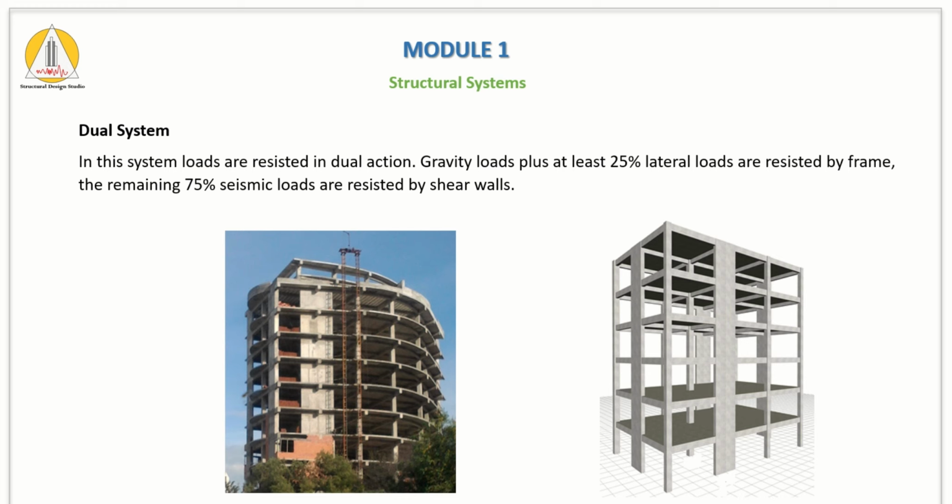In one, we will design only the frame for the gravity loads, and the shear walls will only support the seismic loads, but not the gravity loads. The earthquake loads will not be applied on this model. The next model will consist of only the seismic forces, and the columns and beams will only contribute to complete the structure.